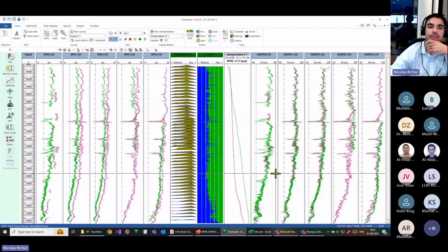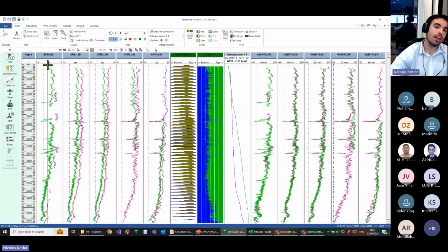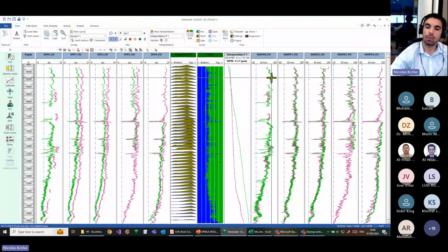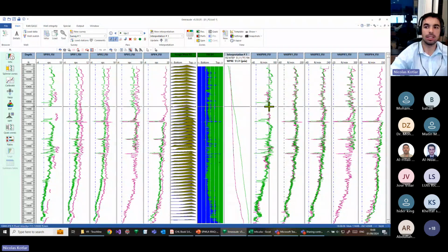And there you go. Can you see on the left side, I have the FSI spinners, and the units are RPS. So these are the revolutions per second, the raw data measured by the spinner. On the right, I have the FSI spinner velocities, right? The computed velocities. So now I know actually what's the fluid velocity as measured by each individual spinner. Okay.